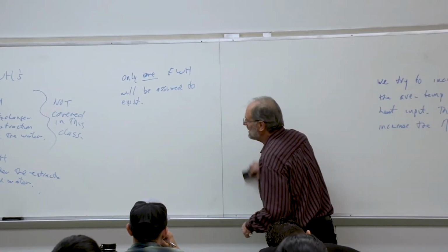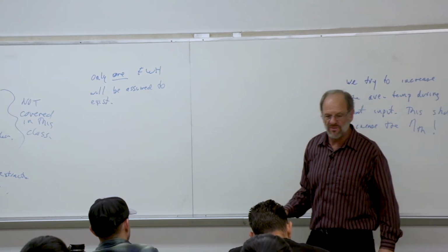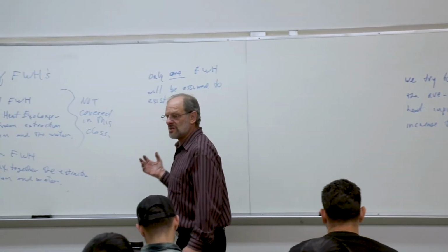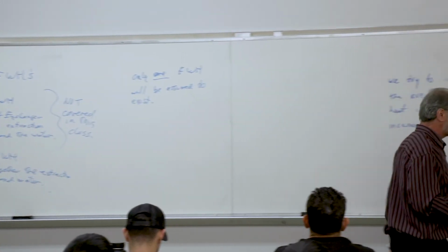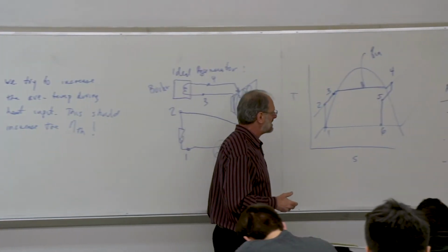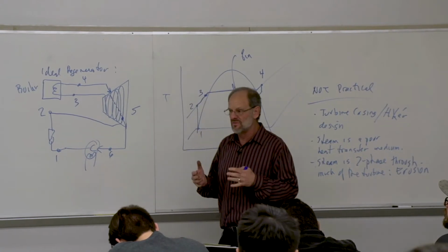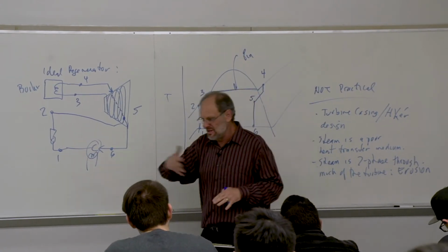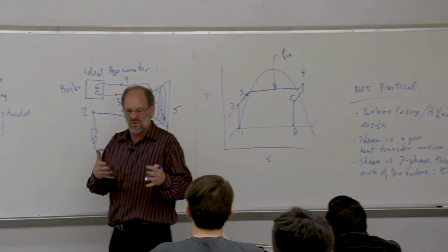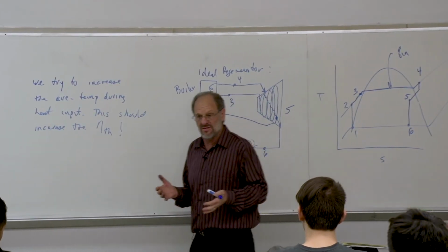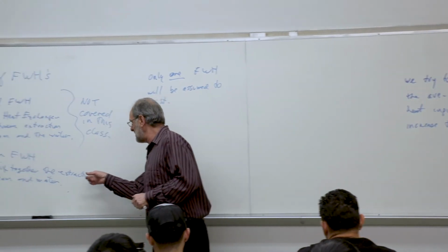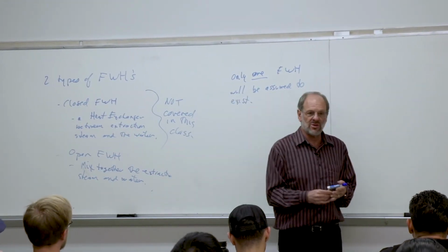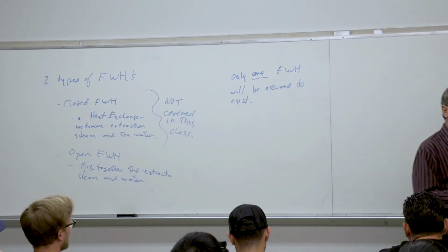In fact, even before I get into that, let me make one other comment about the open feedwater heaters. They really serve two purposes, one of which has absolutely nothing to do with the thermodynamics, but is incredibly important, and it actually has to do with the quality of the water. And I'm not talking about quality in the context of liquid versus vapor. I'm talking about the purity of the water. And it's not minerals that I'm worried about, it's air that I'm worried about.